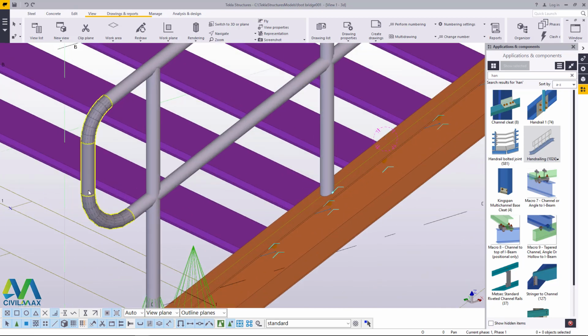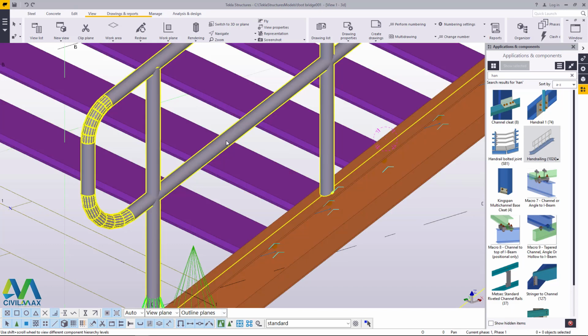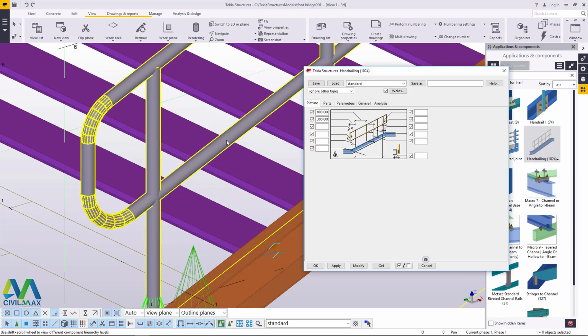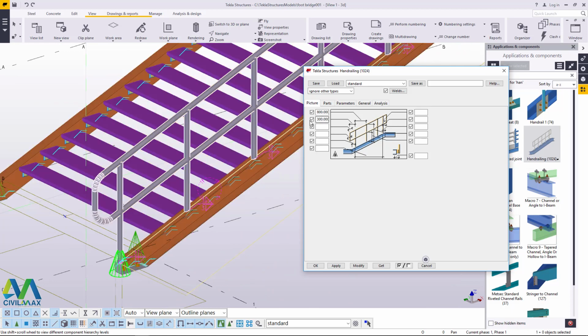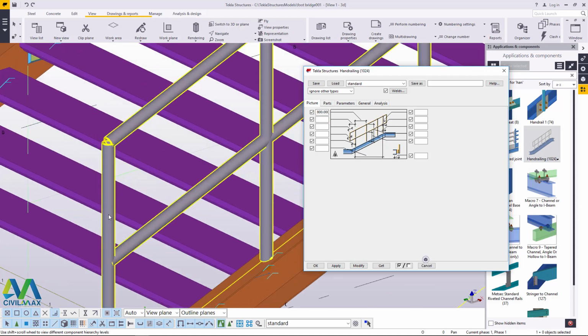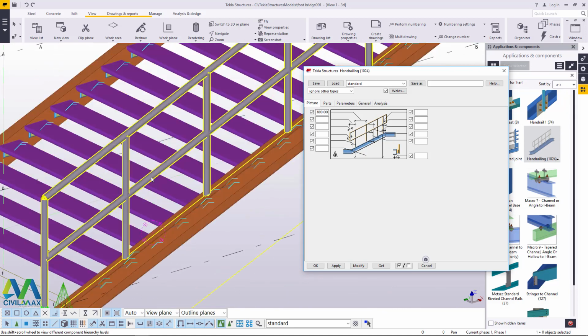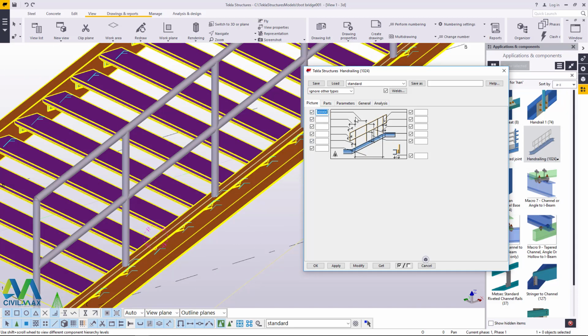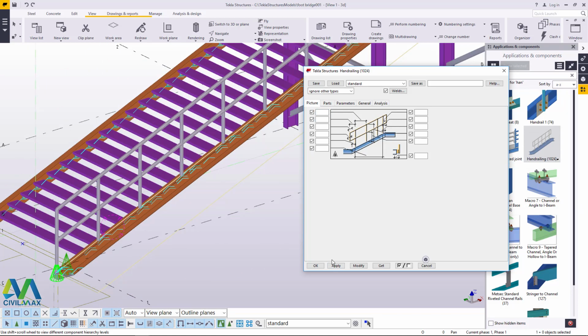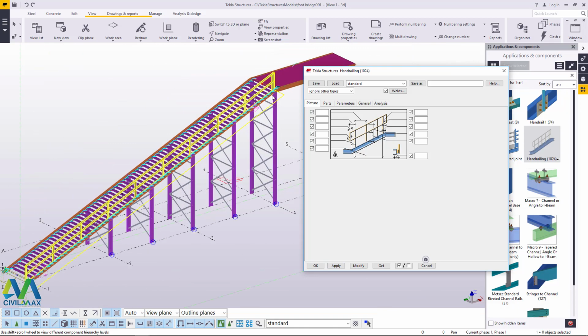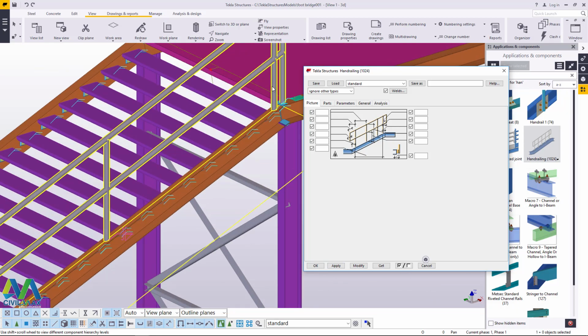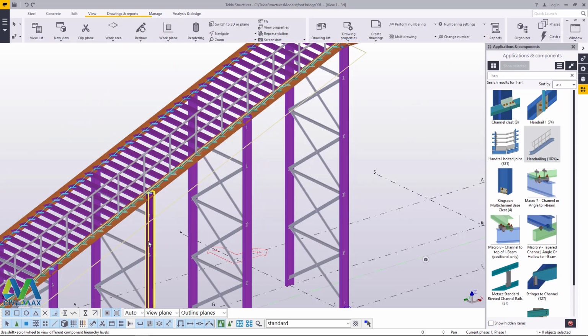You may wonder how this has come about. This is simple. It's simply done like this. I'll double click so that we can access the dialog properties of this particular handrail, and this is how these handrailings are coming up. If I get rid of this and get rid of any number, you cannot see that. And also the spacing of the post is adjusted right here. If I get rid of that, you'll be able to see something awkward presenting itself, which might not look even close to what we want to do. Now we'll bring back our dimensions here, 800 and 300 right there, and click apply and accept right that way.